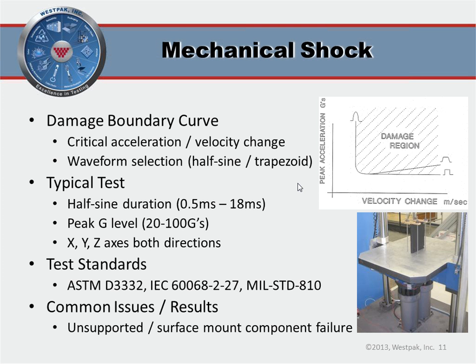It's also important to test all orientations that are likely to get inputs. But because of fixturing constraints, we typically limit that to what we call the orthogonal axes, the X, Y, and Z axes. Both directions are important because you could have different sensitivities of the product, mechanical components, in one orientation versus another, top versus bottom, for example.